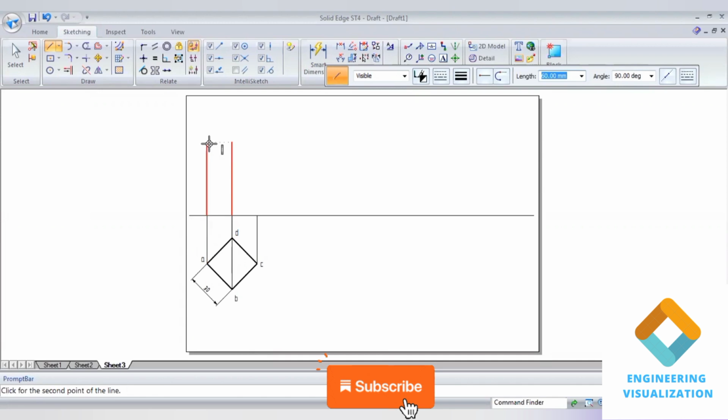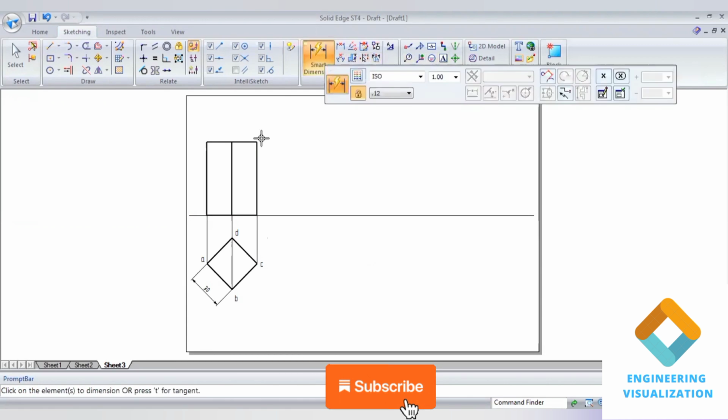It is a square prism, which means we have to get a rectangular face in the front view. Okay, so the front and top view of the square prism is done. Now we can show the dimensions.